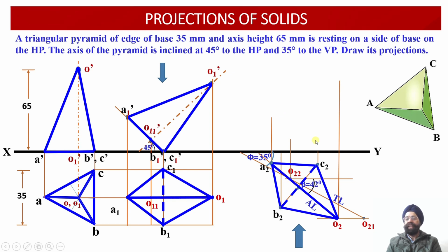We can draw the vertical projectors in the upward direction, and we need to find the corresponding points of intersection of these vertical projector lines with the horizontal projectors, which will emerge from the corresponding 5 points of the previous elevation projection view. So now let us start evaluating the elevation projections corresponding to the oblique triangular pyramid.